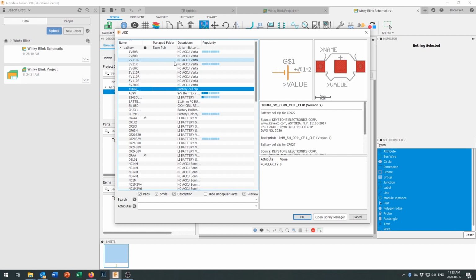If you see red pads like that, now for most of the stuff you're going to make in the high school shop, red pads are a warning. Stay away from the red pads. They're actually really useful in industry. They're surface mount pads, and you can certainly design homemade boards and high school shop made boards using surface mount components, but we're not doing that right now. We'll come back to that later on in a future lesson.